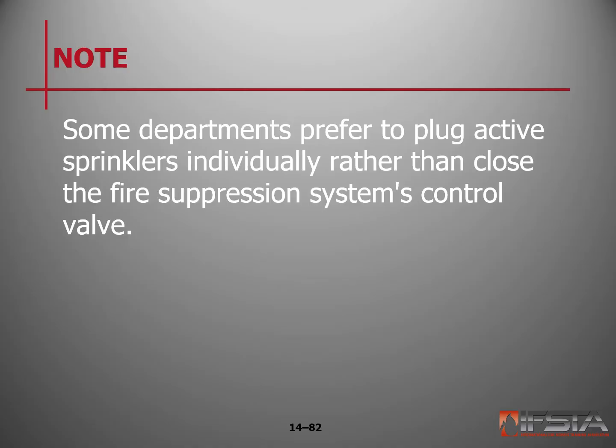Some departments will prefer to plug active sprinklers individually rather than close the fire suppression system's main control valve. This is done typically with wood wedges. They do make commercial devices for this that can also be utilized. The cheap and inexpensive way is wood wedges.